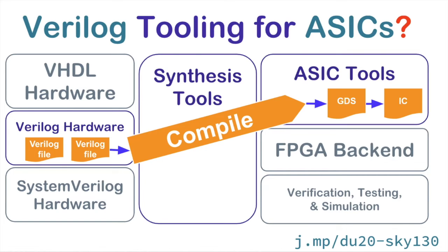In the process, we also need to do DRC, LVS, compile the clock tree, and divide the power domain, and so on. Whatever, we got the GDS file at last. And we will provide it to the foundry, and they will help us to manufacture the ASIC.